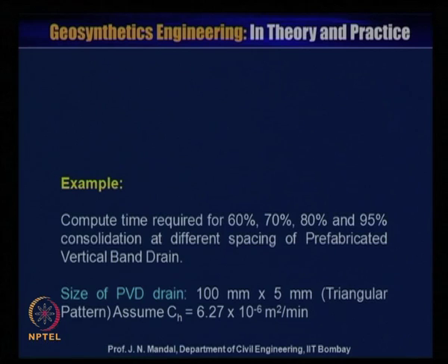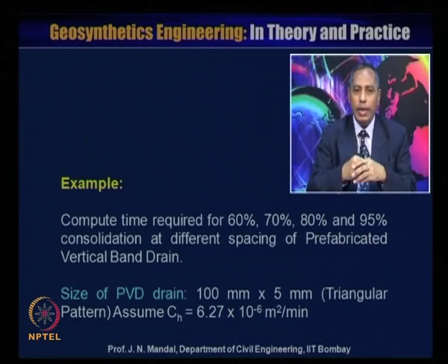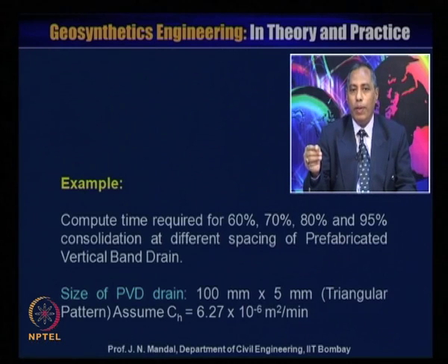Now, we are showing one example. Compute the time required for 60%, 70%, 80% and 95% consolidation at different spacings of prefabricated band drain.